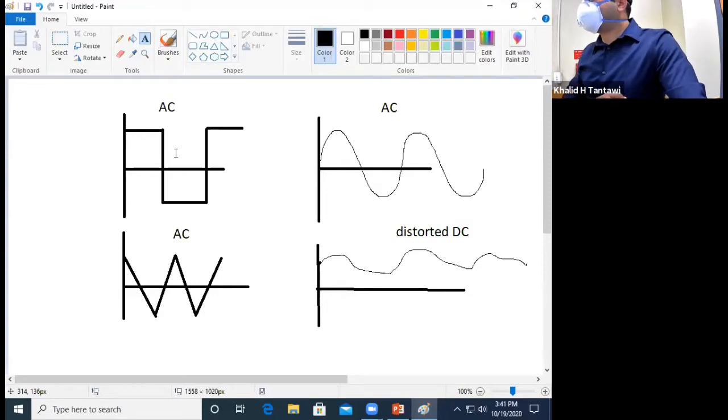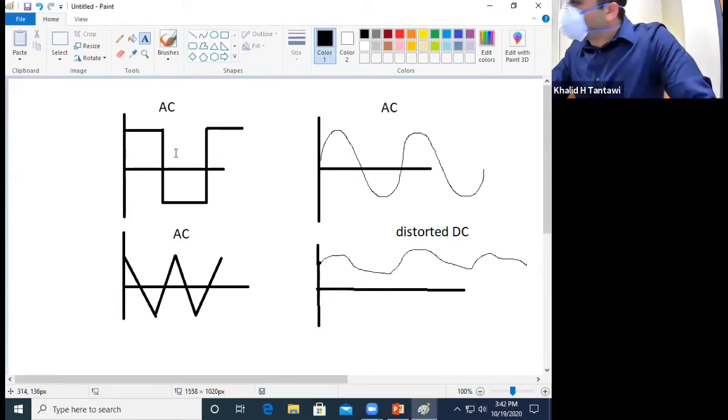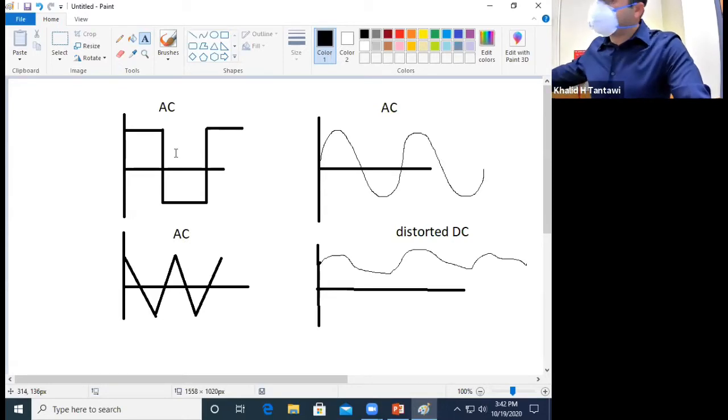What happens to the rest of the remaining sinusoids? They all go to generate heating and pulsation. They're called harmonics. Only the fundamental sinusoid, the strongest one, will give you the torque, and the rest will generate harmonics. In other words, it's going to be inefficient. So to get rid of that, they will always supply you with a sinusoidal waveform.